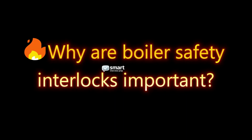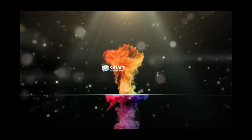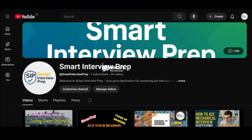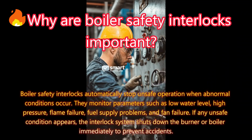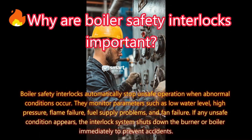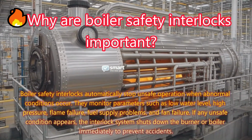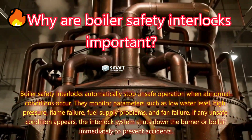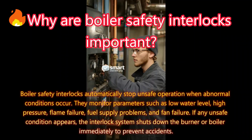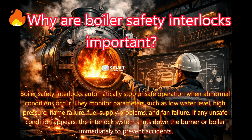Why are boiler safety interlocks important? Answer: boiler safety interlocks automatically stop unsafe operation when abnormal conditions occur. They monitor parameters such as low water level, high pressure, flame failure, fuel supply problems, and fan failure. If any unsafe condition appears, the interlock system shuts down the burner or boiler immediately to prevent accidents.